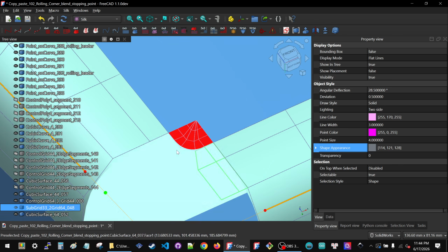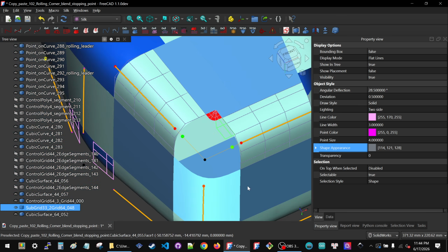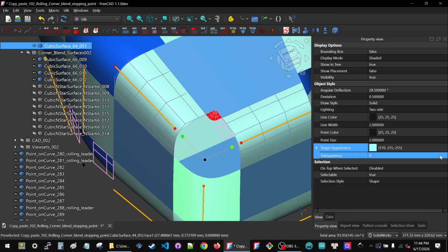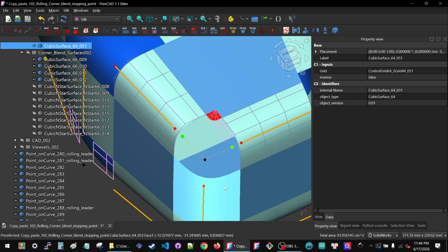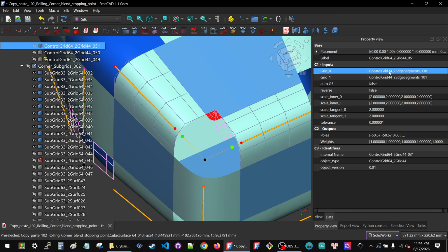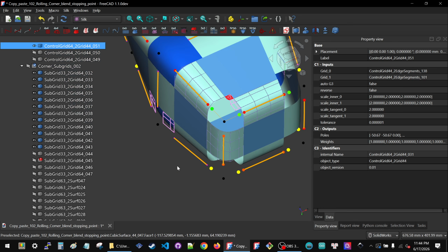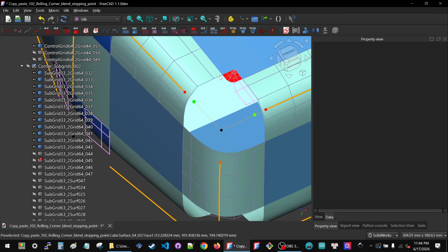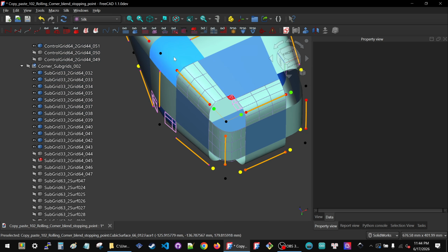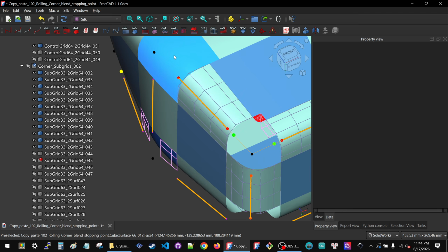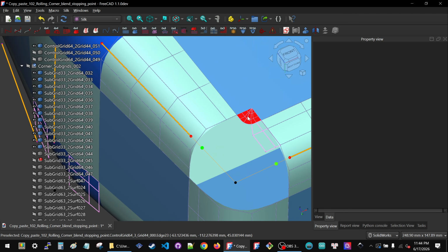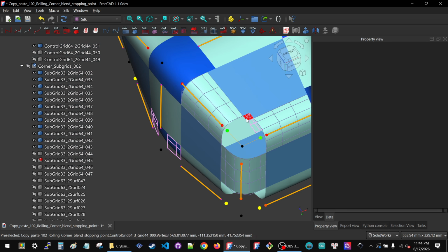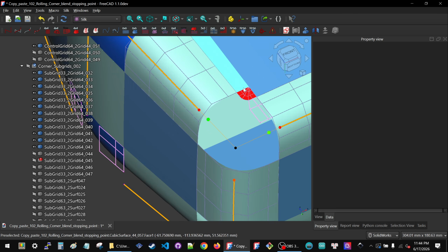Now I'm going to go around the loop and make the subgrids. I'm going to need the grid for this one here. So I select the edge blend, and in here it tells me which one is its blending grid. I click it twice, and now I can hit spacebar to turn it on. I'm not going to edit it, but I'm going to go around this newly 4-sided hole to make a corner blend just like this one. This piece here fakes having an edge blend in this area. And now that I have 4 blends, I can use the standard higher quality blend.